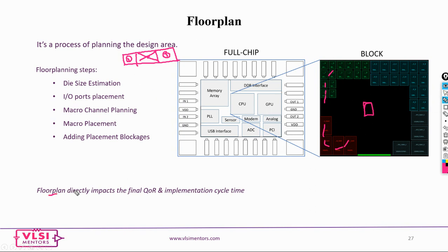And remember, floor plan directly impacts your final QOR and implementation cycle time. If your floor plan is correct, or if you get a good floor plan, 60% of the work is done. You don't need to struggle. A good floor plan helps a lot in terms of design closure.